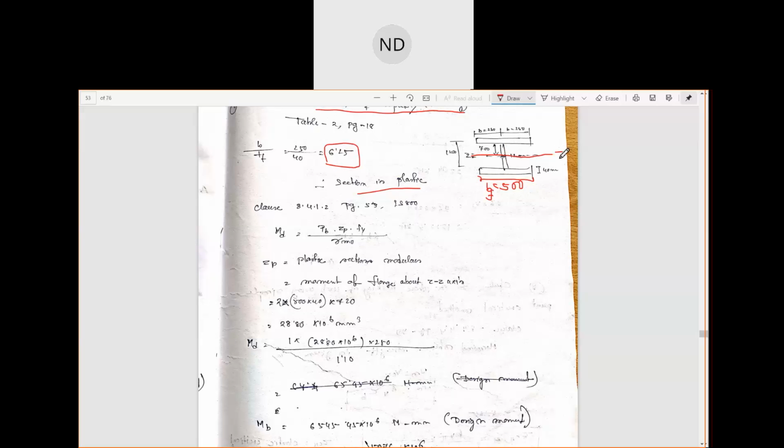So, this is your section modulus Z. Sorry, this is the axis, Z axis. Now, this we know is uniform on the top and at the bottom. This size is the same in the section, so we can find it out. We can multiply it by 2, and then you see here this is 500. The flange area is how much? 500 into 40, and the moment of this flange from the center is how much? This will be 20 plus this one 700, right?